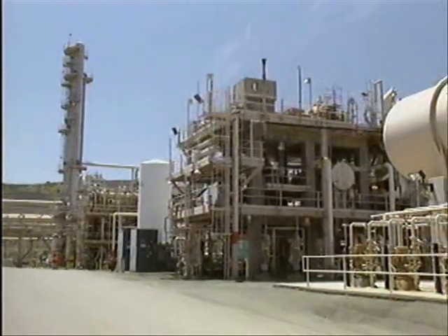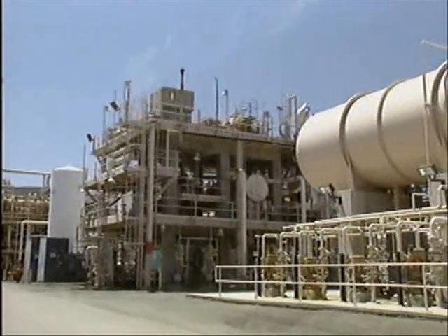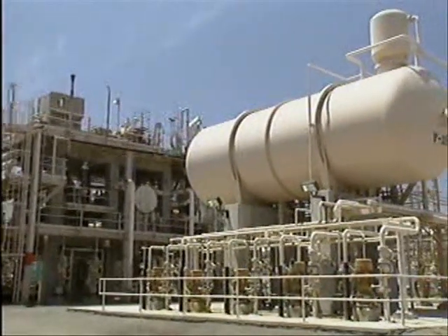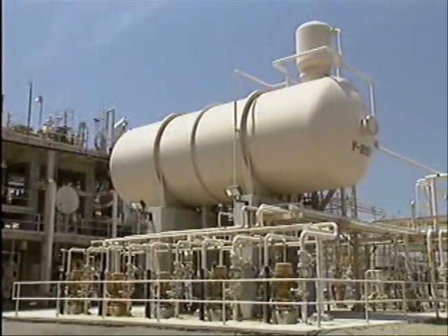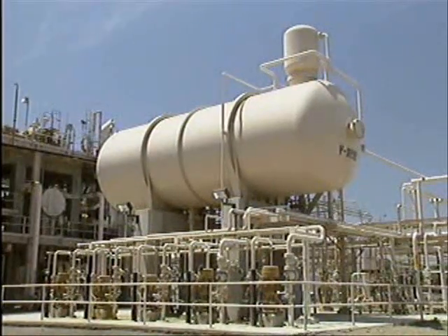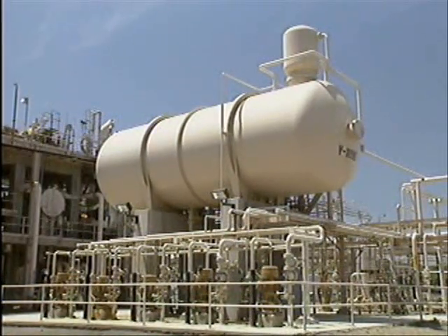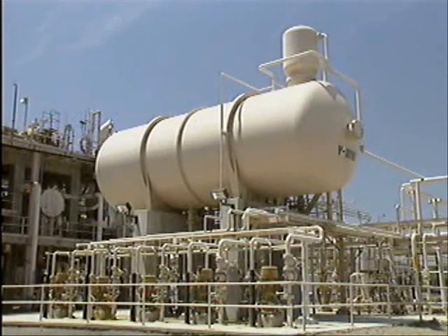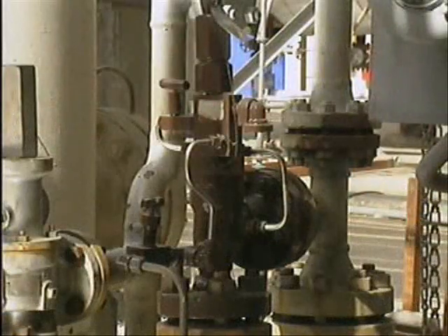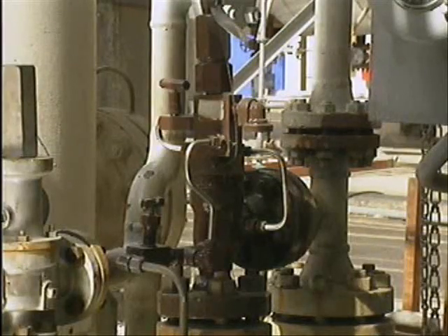valve repairs. You see, by law, safety valves can't be isolated from the systems that they protect because of the damage that could occur if the systems were operated without protection. So, whenever a safety valve is damaged, its system must be shut down while repairs are made. Pilot-actuated relief valves, however, can be isolated from a system because they're not a primary part of the system safeguards. So, the pilot-actuated relief valves can be used and then repaired if necessary without having to shut down the system.